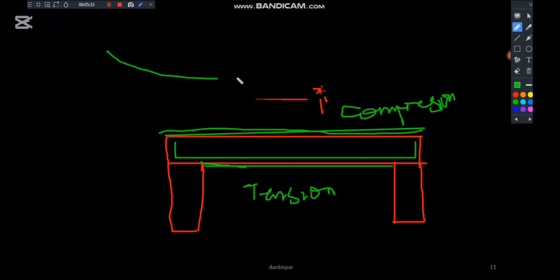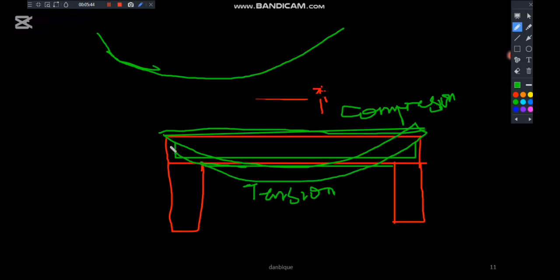So, simply supported beam, this is the theoretical deflection of this beam. Once it bends like this, you know that the beam has deflected. And because of that, you'll find that the bottom of this place, because of the way it's being stretched, this region is under tension. So the upper side is under compression. So what do you do? You design for both tension and compression, and also shear reinforcement. I hope that meets you well. So that's what we're talking about.